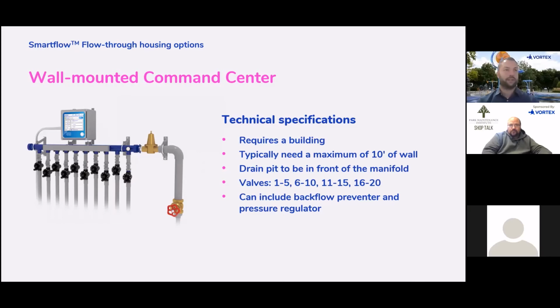Inlet sizes are either going to be 2 inches, 2 by 2, 3 inches, 2 by 3 inches, 4 inches, or 2 by 4 inches. What does the backflow preventer size difference make? Is that just the amount of water that goes through, and so your water pressure, or what does that do? Yeah, that's all going to be directly related to water use.